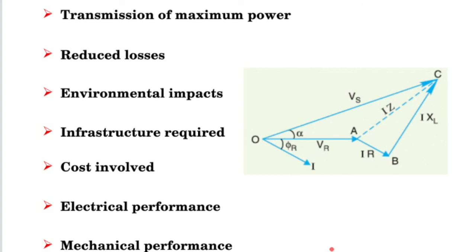So when we string between these two adjacent supports, we need to make sure that they operate for their designed life, and they are always subjected to environmental conditions, ambient temperatures, and pollution that can come from agriculture farms, highways, deserts, or the ocean, or anywhere where they are located. Apart from that, there are changes in the length of the conductor due to temperature, depending on the coefficient of expansion of those conductor materials.